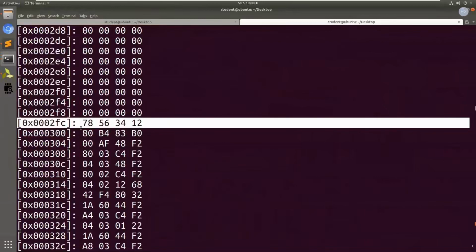I don't know which bit it corrupted. All I know is that it read some value which was not one of the 4 values that locked the device. And how do I know that? Because the device managed to boot in a state where we were able to get into it and dump its contents. So we somehow corrupted this value at the one point in time at which it gets read during boot. That's like a very short intro to glitching.